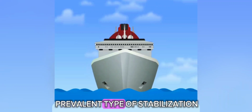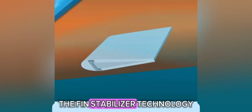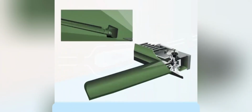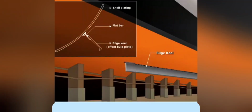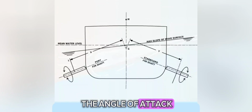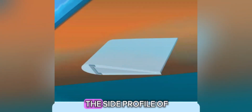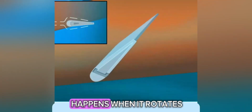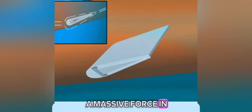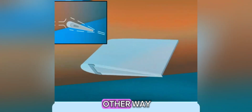This is the most prevalent type of stabilization aboard cruise ships. The fin stabilizer technology comprises a hydraulically driven underwater wing. It resembles the bilge keels. The key difference is that you will be able to modify the angle of attack with these active and dynamic fins. If you look at the side profile of a fin, you can see what happens when it rotates. If you turn it one way, the water flow produces a massive force in one direction. You can instantaneously switch the direction of that force by turning it the other way.